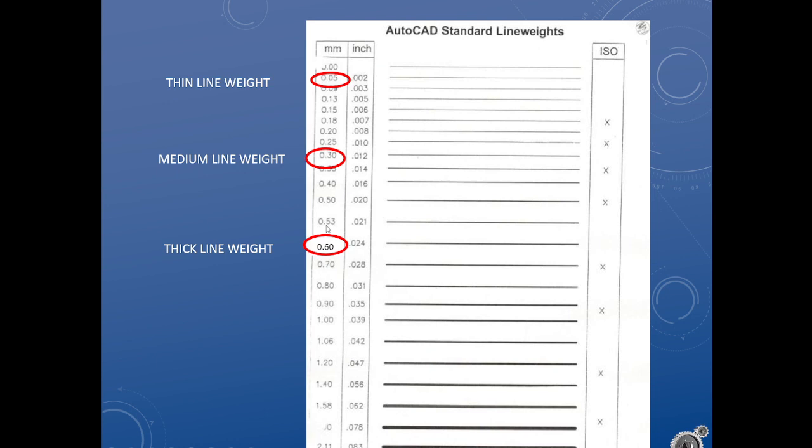Quick rundown of what we mean by thin, medium, and thick. This is a little bit unintuitively the size of pen you are using. So when you draw at 0.6, that's not 0.6 relative to your page. That is a 0.6 millimeter thick pen, which means no matter our zoom level, it's always going to be 0.6 millimeters. Because it's imagining that every time you zoom, you've redrawn your entire picture using the same set of pens. The line weights do not scale by default.